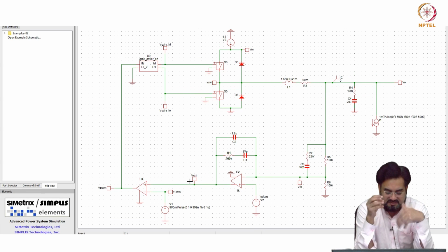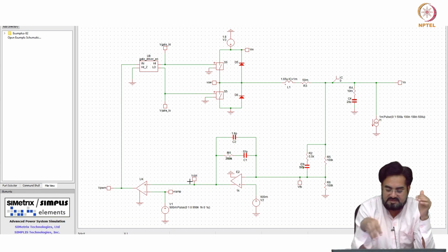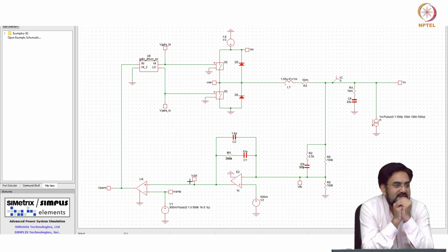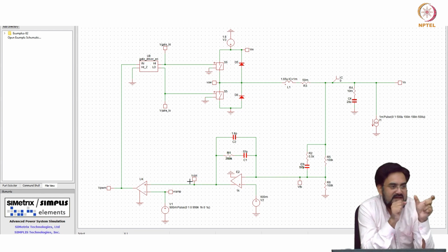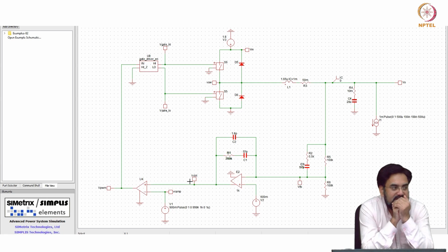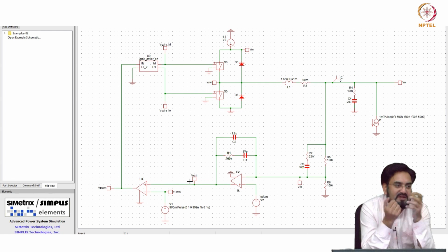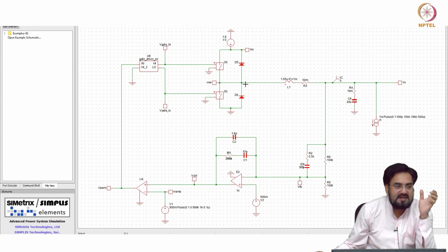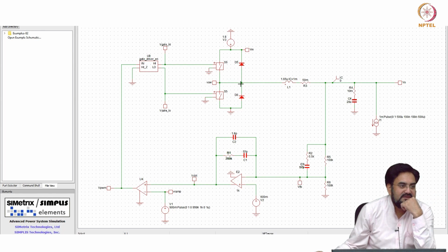No, this will not affect your output, because that ripple is filtered out by the LC. At 1 megahertz, your LC has omega naught very low compared to it, so everything will be filtered out. You will hardly get a portion of that appearing. And why would you get that? That ripple is determined by your duty cycle and frequency, which is not changing.